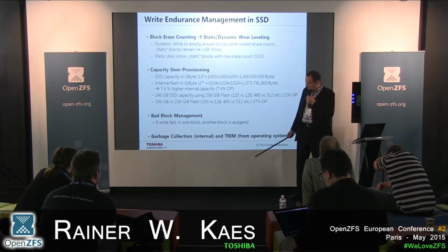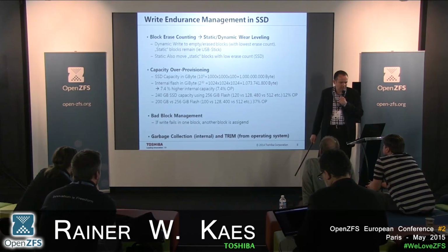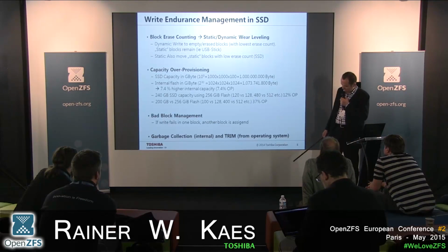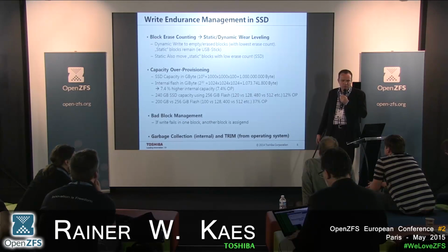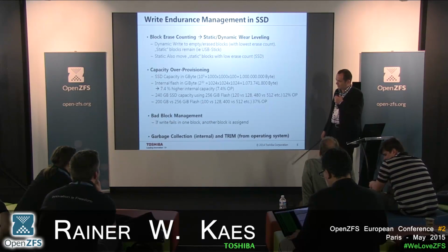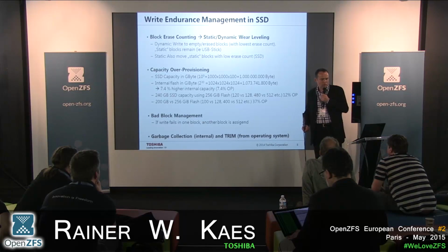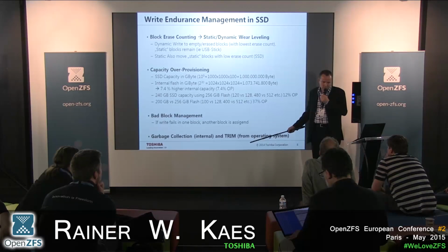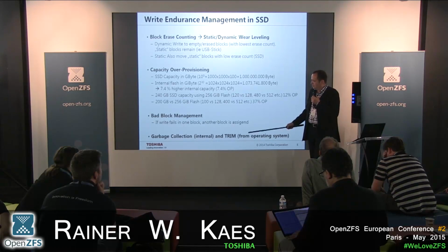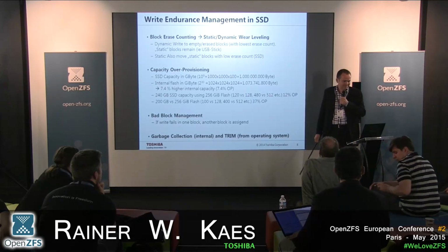Well, the SSD needs to know which data can be erased, and this is the more philosophical discussion about this trimming stuff. And operating systems are still designed for hard disks. For hard disks, we can just overwrite. There's no such process of erasing. So files are labeled as I don't need them anymore, and next time they can be overwritten. In an SSD, the SSD would like to know in order to trigger this kind of pre-erase operation. If it comes from the operating system, it's okay, but in server and RAID applications, this doesn't really work. Well, I'm going to have some questions about that after.